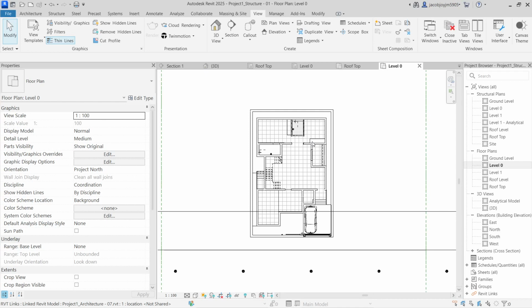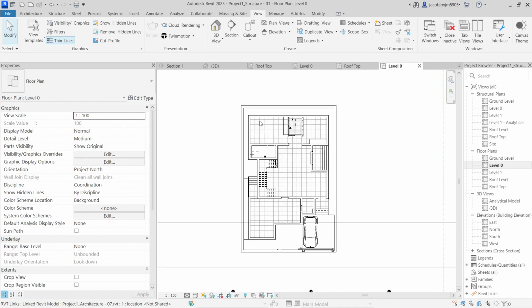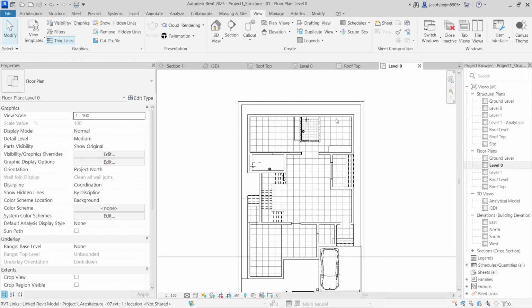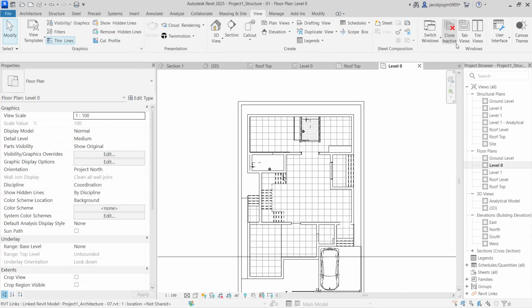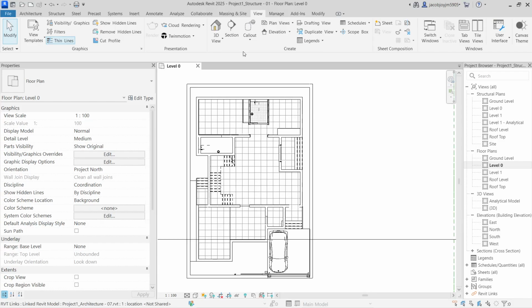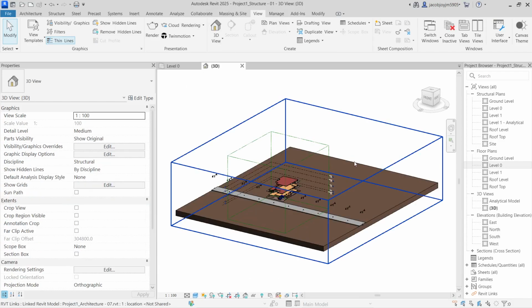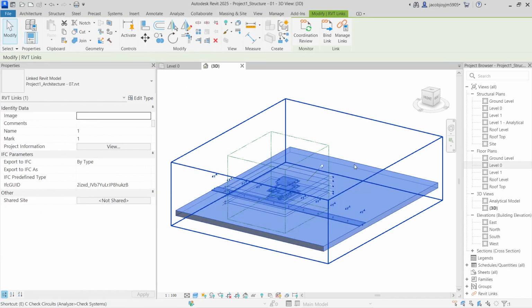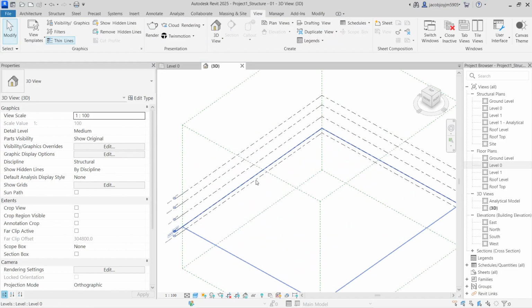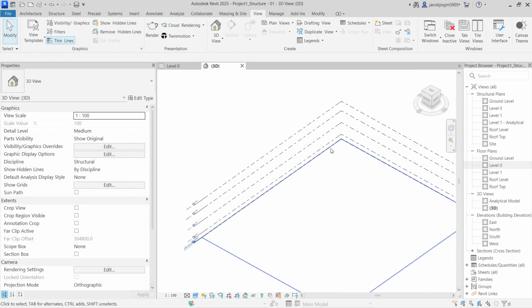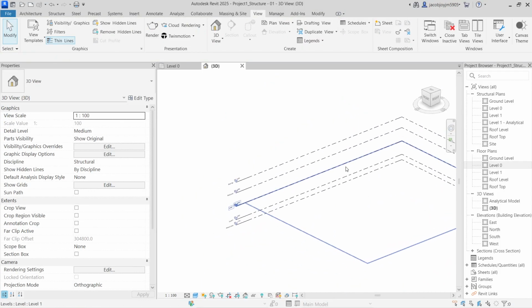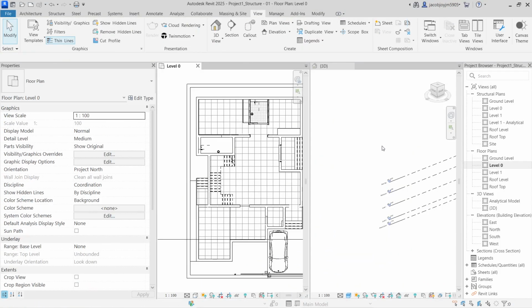I'm going to draw the beams. So how I'm going to draw the beam? Wherever the wall is coming, the beam is going to come. That's it. A very simple method. Go to structure. So if you want to see them clearly, close inactive, take a 3D view. I've just hidden the architecture link. Hide in view category. The levels, let it be.